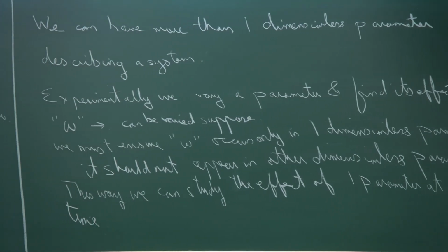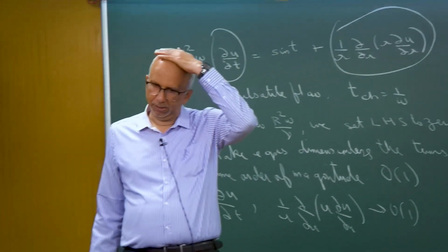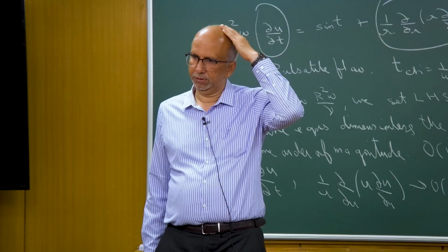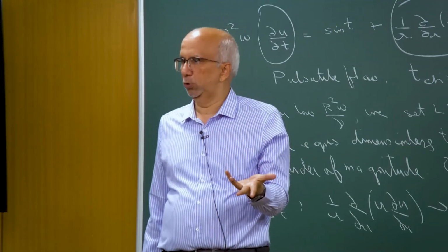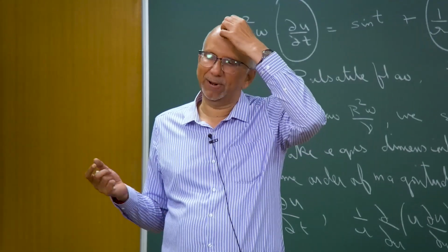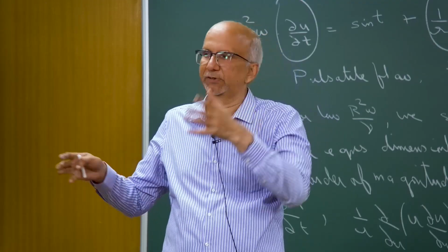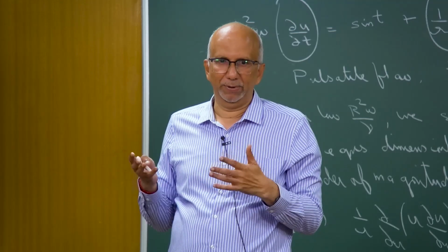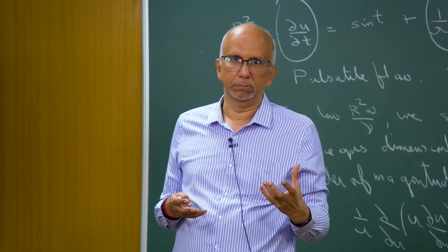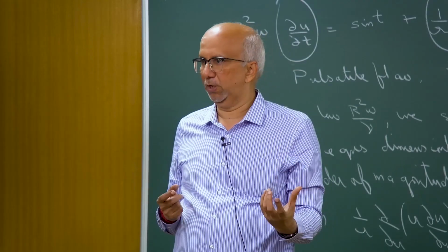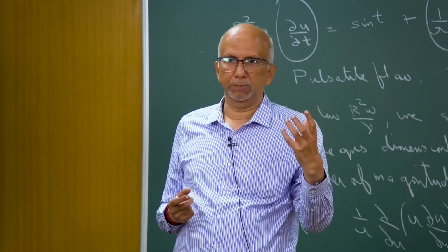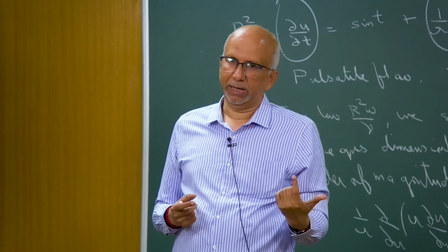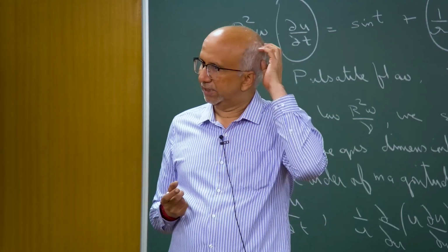Okay. So, I mean, there are just a couple of things which I thought you should keep in mind, because if you say you are studying the effect of Strouhal number, and experimentally how do you do it? I mean, this is just not a mathematical exercise. I have 4 dimensional parameters, I fix 4 and then I am varying 1. Mathematically, yeah, but experimentally, if you want to make sense, because you are representing a physical problem. Okay. So, is it really possible to change only Strouhal number? Yes, if omega, because your R is going to be fixed, okay, the radius of the pipe, your nu kinematic viscosity is fixed, the only thing which you can vary experimentally is omega.